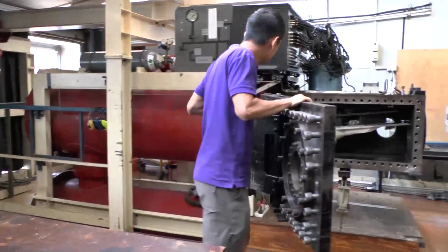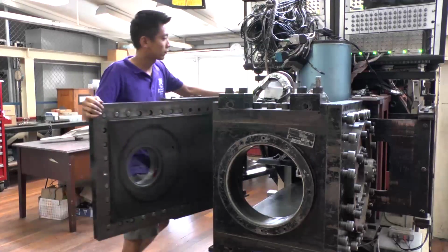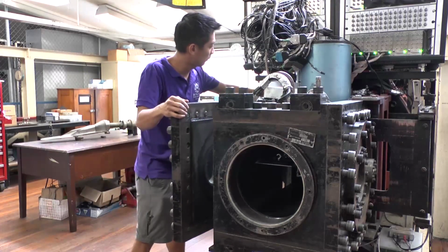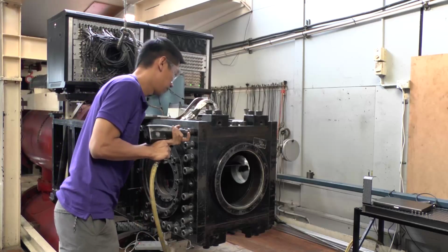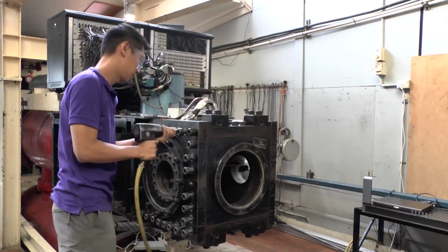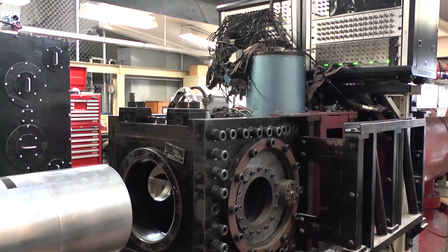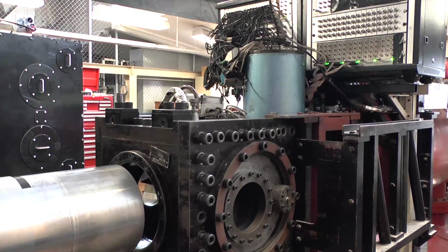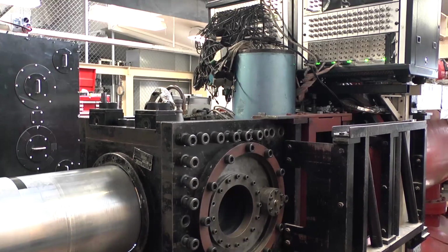And so what we're going to do now, we've learned about the tunnel, is we're going to go into the control room where we control the test, and we'll experience an actual shot in T4. In preparation for a shot, there's a number of tasks the experimenter must perform. The test section must first be closed and then firmly sealed with a large array of bolts. The entire test section is now moved slowly forward, smoothly connecting to the exit of the hypersonic nozzle.